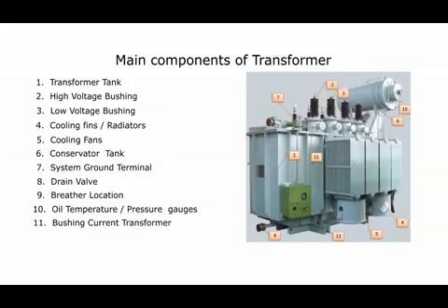These are usually found around the transformer terminals, which will later be used for metering and relaying purposes. Its terminals are found in the control panels attached to the transformer. Control panel houses all of the transformer's monitoring devices, terminals, and auxiliary devices, including the terminals of the bushing current transformers and cooling fans.